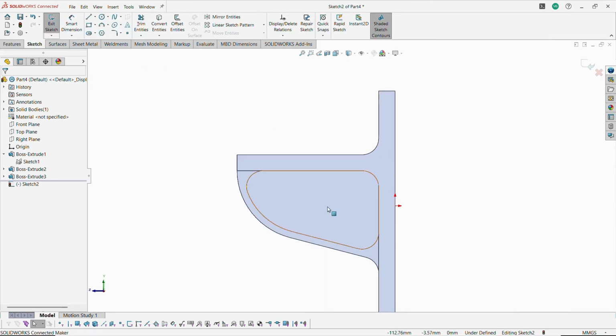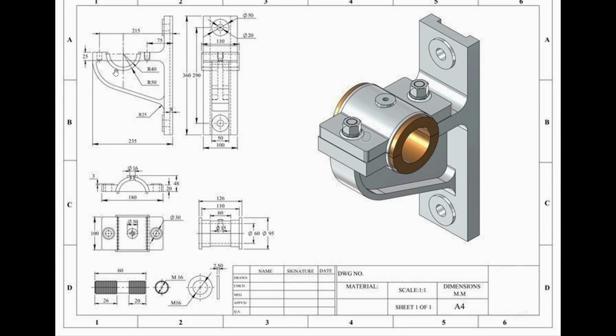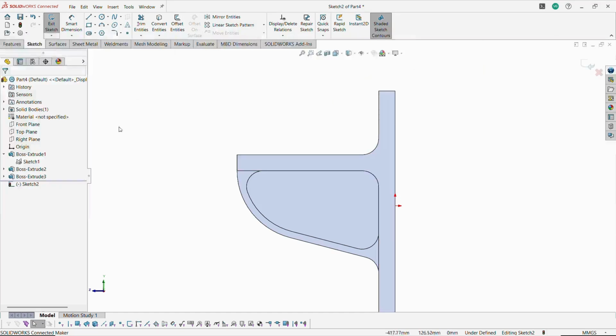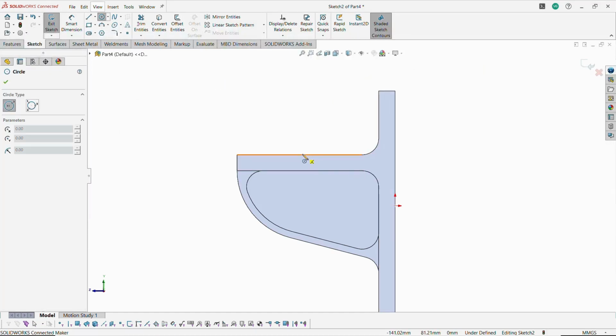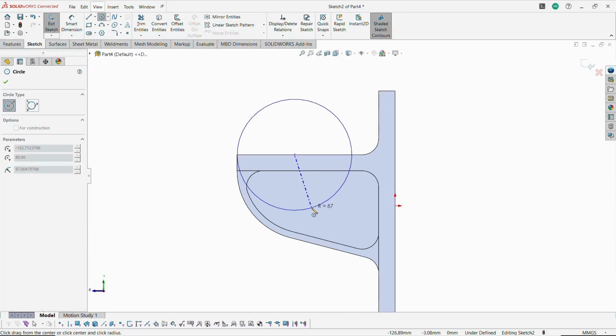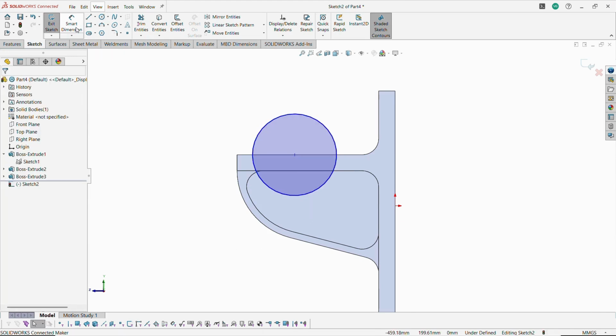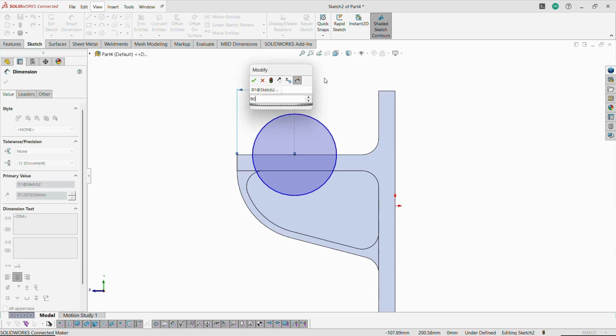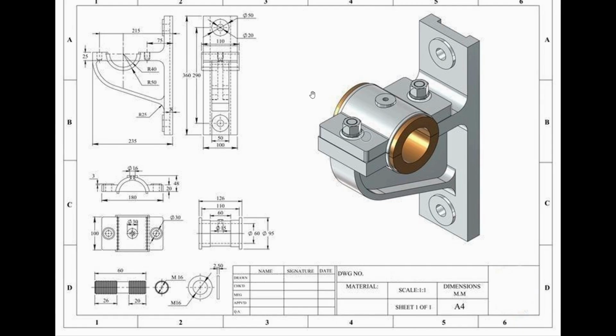Once the solid portion is created, now choose this particular face and create a new sketch. Then draw one circular profile. We are going to eliminate some excess body. Either you can create an R profile. Now I am going to draw a circular profile in this portion. There are 2 different radii. First initiate the last one, that is a 50 mm radius. We are going to eliminate the body using this radius. So selecting 2 opposite points and initiate the dimension of 90 mm.